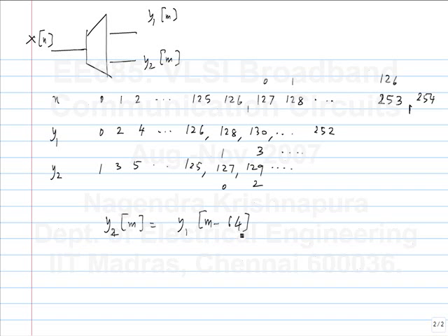You have to take the summation over 127 bits and show that it's 127 when they are overlapping, and when it's not overlapping, it's -1. So that doesn't show that it's the same pseudo-random sequence, but it shows that it has a white noise-like property. Okay. So in this case, it's not just that; it is even stronger. It's the same sequence that you get. Yeah, that's why I said if I had not mentioned autocorrelation in the problem, life would have been easier for everybody.